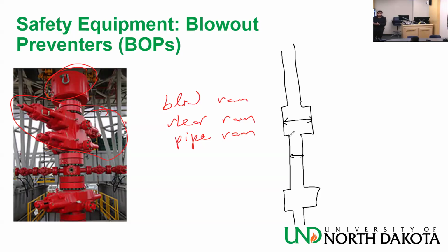It's a good process, like always. You lift off the bottom and then you shut in the well. But you generally lift until you see the first tool joint. Then you know, okay, I'm safe inside. I don't have a tool joint in my BOP. I can use whatever ram I want.